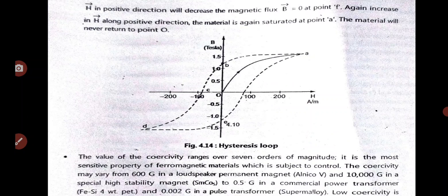We have already seen that the material placed in the magnetic field is magnetized and shows the high saturation point, which is considered A. And if we decrease the value of H, the point on the vertical axis at point B is where H is 0, the point on the dotted line. But the material is still holding some magnetism. At a negative value of the magnetic field strength H, the overall magnetism of the material is reduced, and that point is called the coercivity.